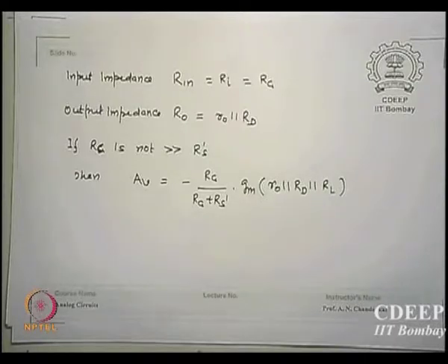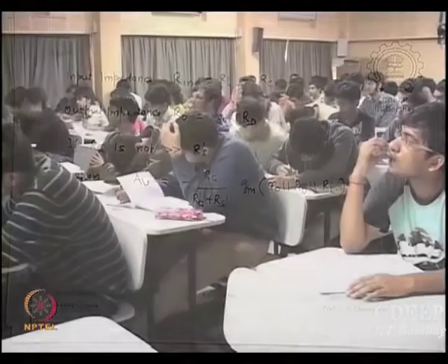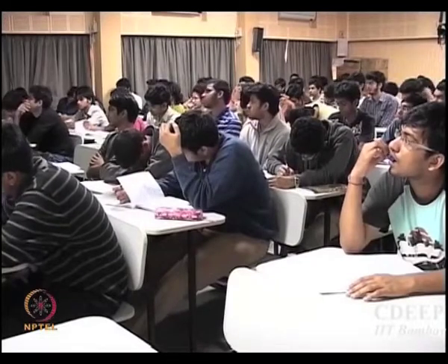What do you believe, which will have the highest voltage gain? In the common gate, the gate is common to source and drain. Whatever is at the source will pass to the drain. The source and drain current is the same, no? So it is roughly unity. It depends on the load values at the input and output. The current is the same on both sides, is that correct? So it will depend on the values of RD and Rs you actually use, whereas there is no gm factor, there is no booster there.